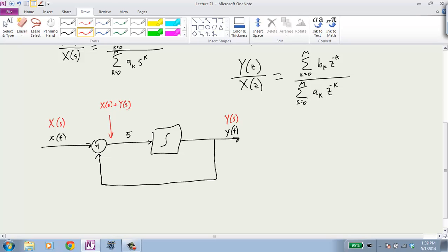And then we get times 5 here, and then the integral just becomes a times 1 over s. So an integrator in the Laplace domain is just 1 over s. It's just multiply by 1 over s. Right? All right, so 1 over s times 5. Better make my 5s look different than s's. Okay, and then we get our equation. Same thing we ended up with last time.